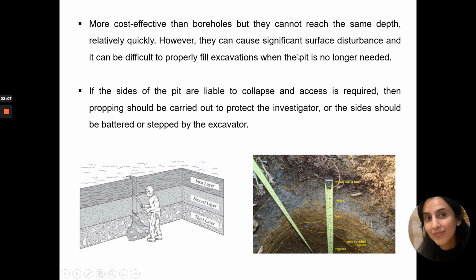Okay, itu sebab dia kata significant surface disturbance. If the sides of the pit are liable to collapse and access is required, then propping should be carried out, because there are cases where when people excavate manually the trench or the pit, there is a very slight landslide, but it caused death.